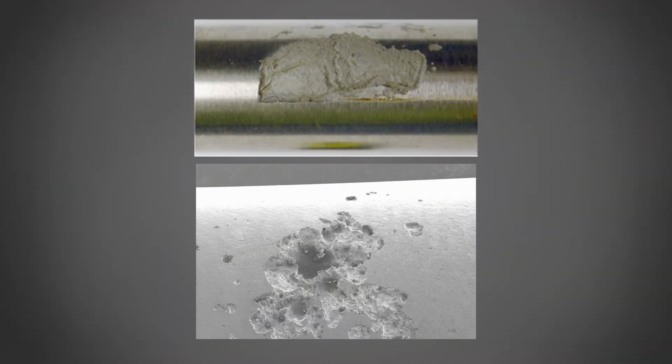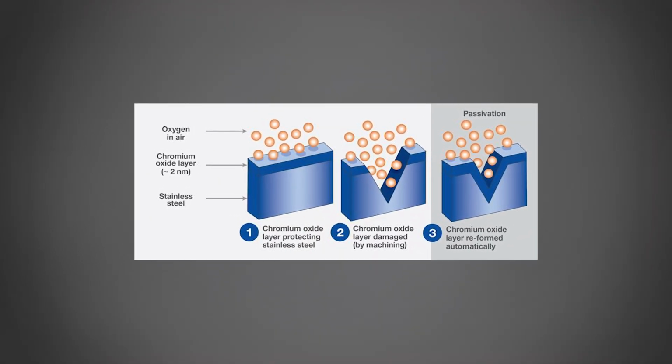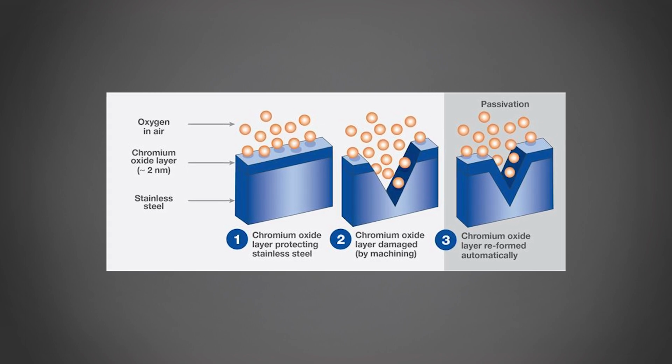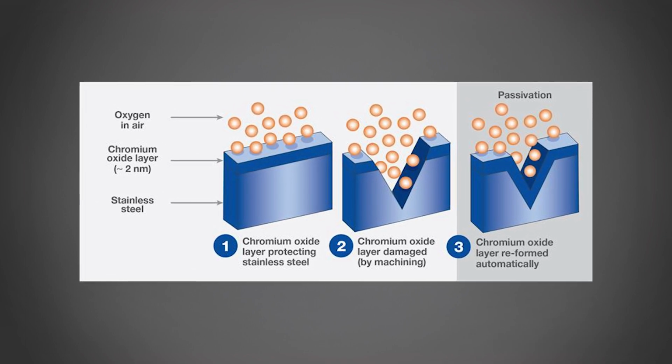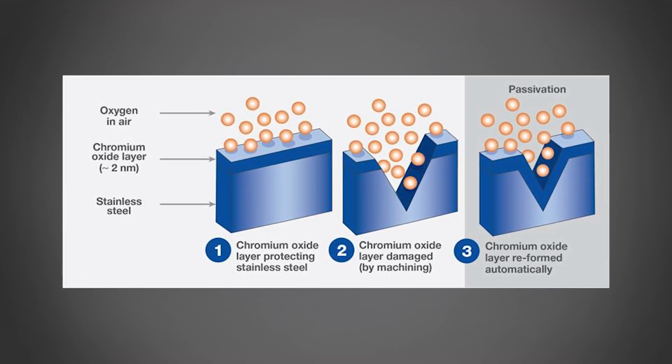So, for example, if you have a pitting or crevice corrosion problem, understanding the effect of the passive oxide film on the surface and its ability to resist pitting or crevice corrosion cracking allows you to understand that choosing an alloy with a higher chrome or molybdenum or nitrogen or all three will provide a more robust solution in that environment.